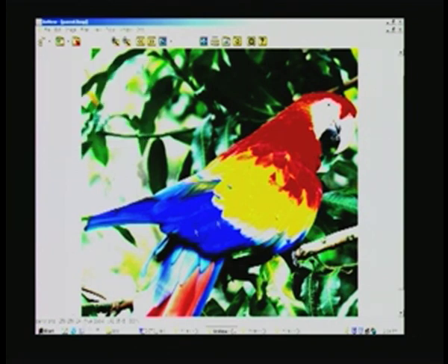If you zoom both these pictures, for example the first high resolution picture, you will get all squares, and each of these squares is known as a pixel. A collection of 64 pixels, that is 8 by 8 pixels, we take in order to process a DCTQ, and that is referred to as a block. A block consists of 8 by 8 pixels, and if you examine each pixel very closely, you will see that one particular square has only one common intensity all through, because it is a pixel.